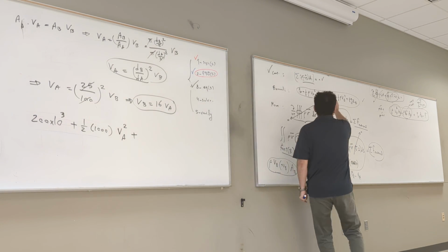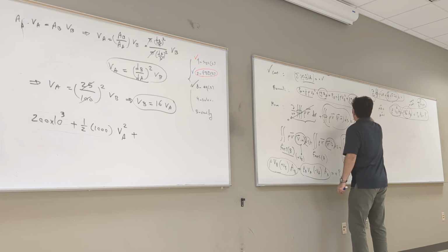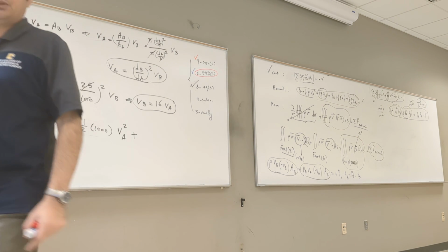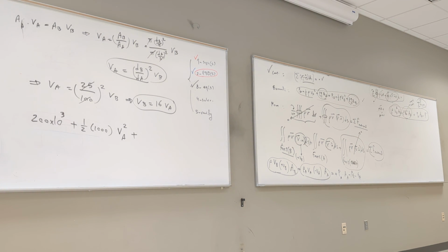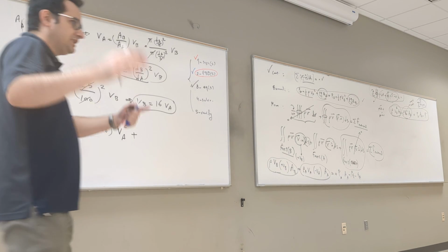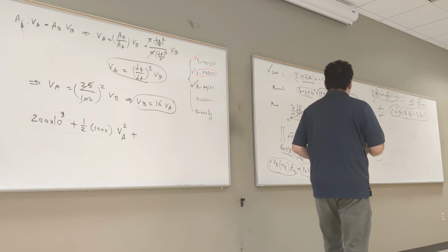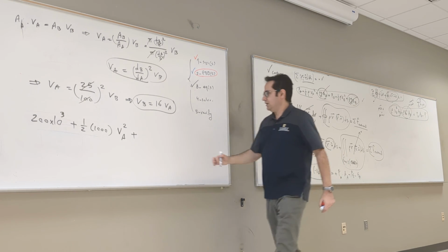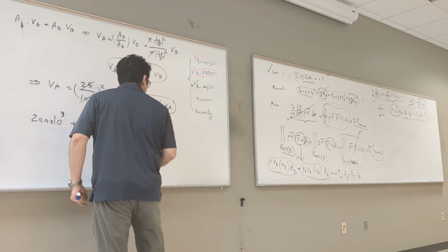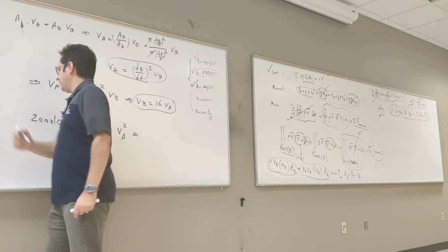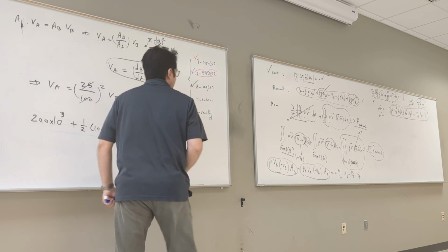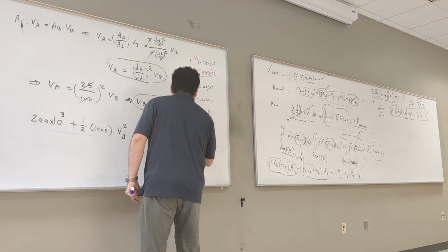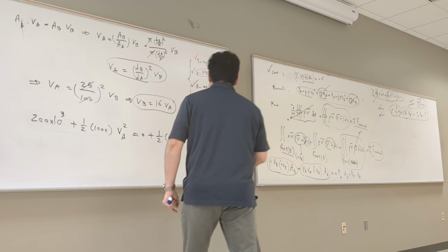Look at these two terms, rho g ZA and rho g ZB. Is there a difference between ZB and ZA? No. Why? Because it's just flat. Again, if you don't understand that, you need to come to my office, please. It's too late. So these two terms don't exist. So you go to PB. What's the pressure at B? 0. Plus 1/2 of 1000 times VB squared.